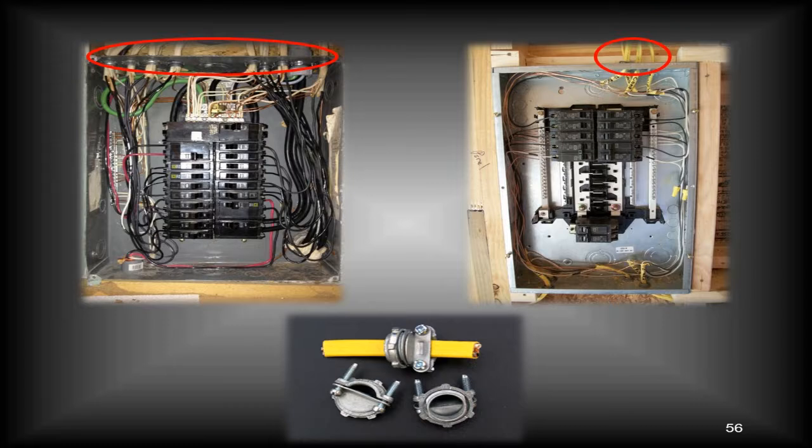When you go from older residential dwellings to newer residential dwellings, we have so many new circuits that people didn't have decades ago. We have a lot more things that plug in. We have ceiling fans, lighting everywhere, special stuff that they just didn't have room in the old boxes for us to hook up all of this new stuff. And so you'll see guys that'll go in there, do a renovation or something, and they'll have to double lug or change the box.